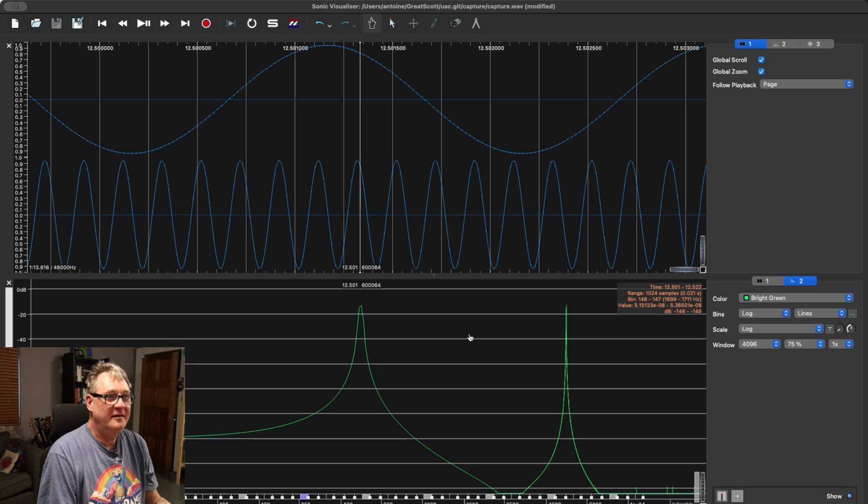So yeah, it's pretty simple. If you look at UAC in this way, you've got the descriptors, which are specified in the specification. You've got to implement those. And then you've got 3 endpoints that are actually transferring the data. Do those, and we should be able to build an audio interface. Let's give it a go.